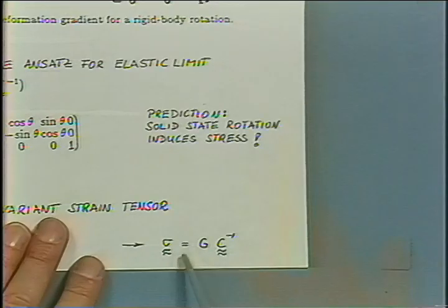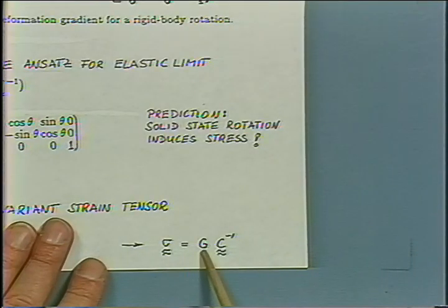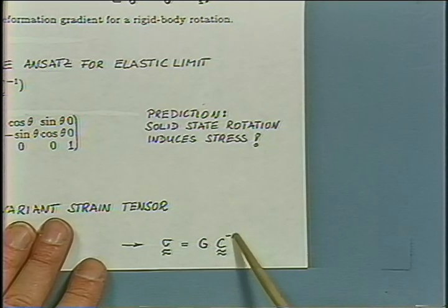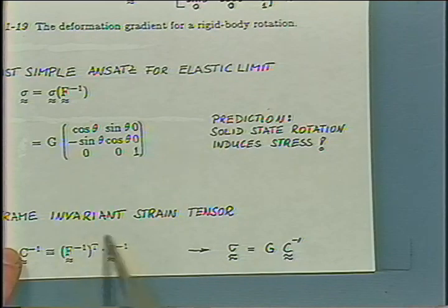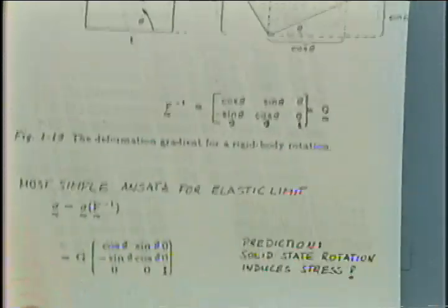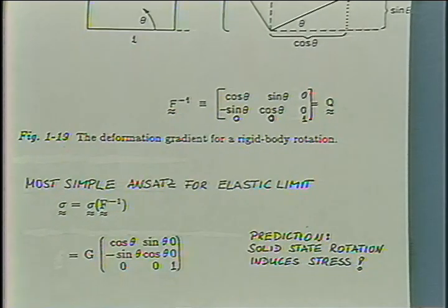So we could say that the stress is equal to the modulus times the Finger strain tensor. And when you evaluate this product here for this matrix, then you will find that this matrix is equal to the unit matrix at all angles theta.